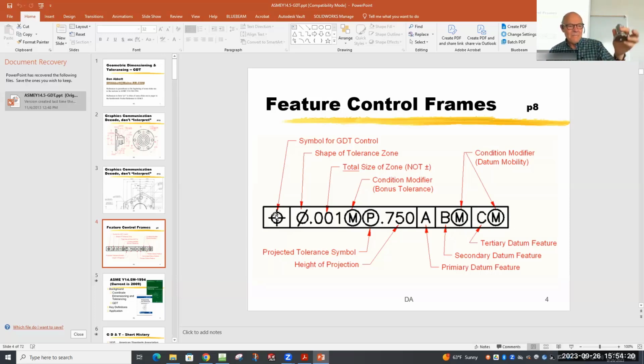So they said, yes. The problem is that part right there had a huge amount of money invested in it already. The equipment to make it was expensive. The cost of the people who machined it was high. They got way into the process before they got that nick in there. And so that process of making that cost them a lot of money because the tolerances on this were so small. But that's a small tolerance, and that's the tolerance for position. So you can have a hole that's out of position, but it can't be out of position more than 1/3 of a human hair. Make sense?